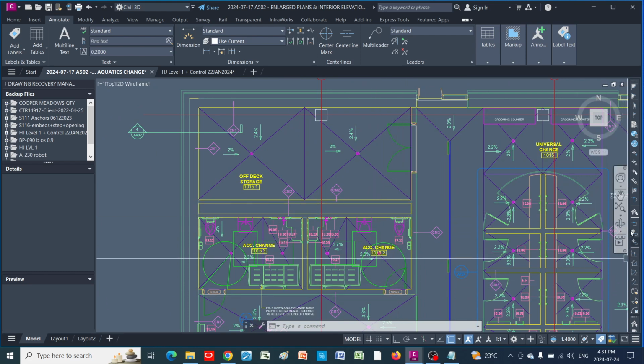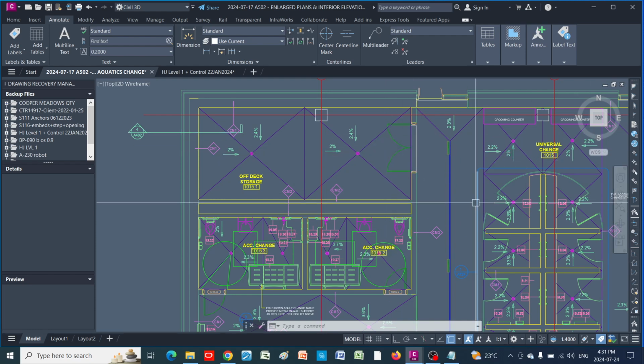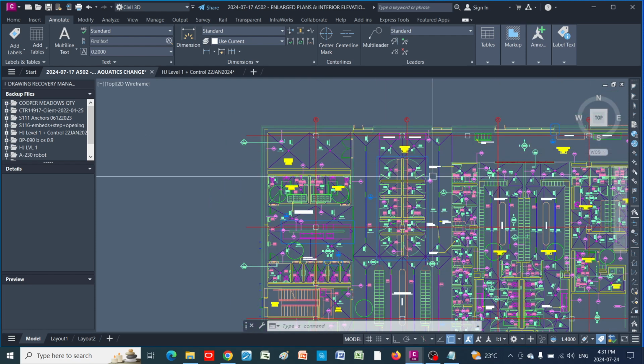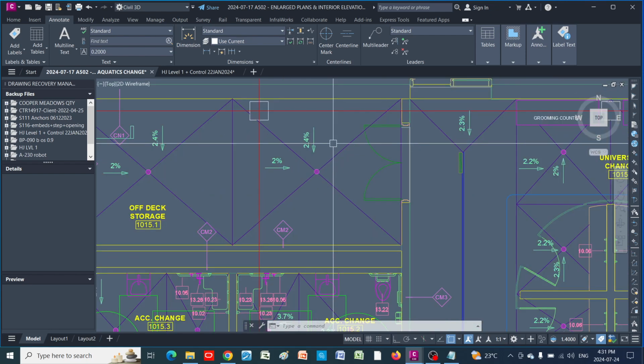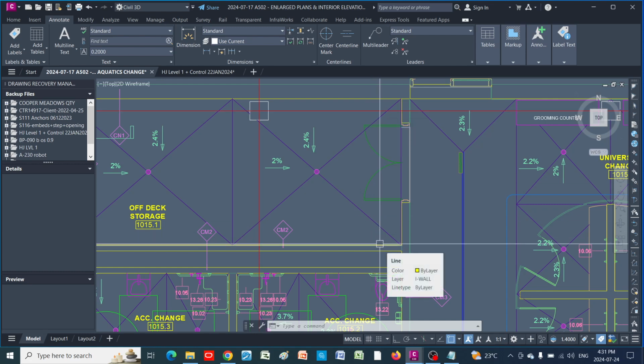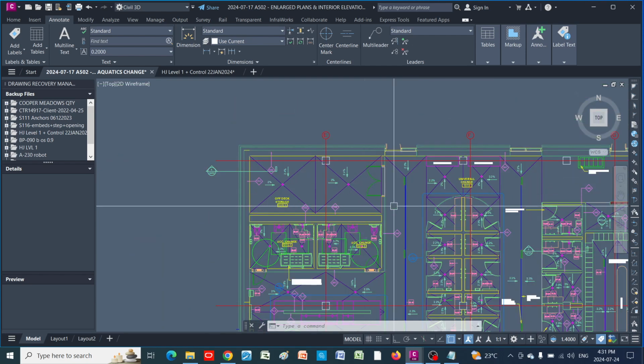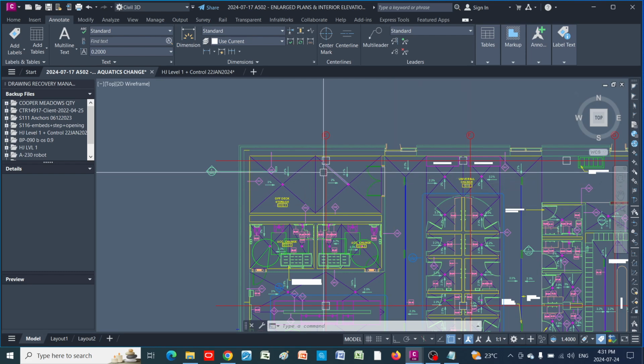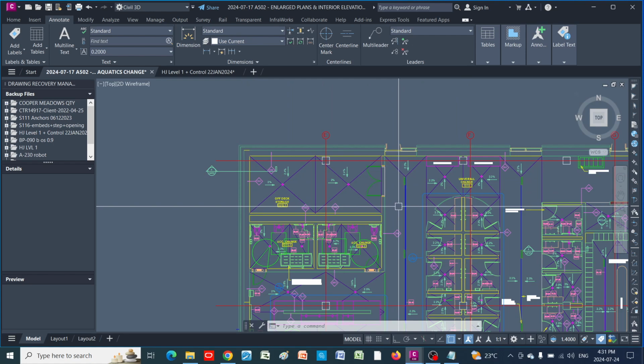What I'm gonna do is measure the distance from grid line 2 to mark this one. So in the olden days, we called the surveyor to mark the grid lines, and then we did our layout by measuring from the grid line that the surveyor marked.